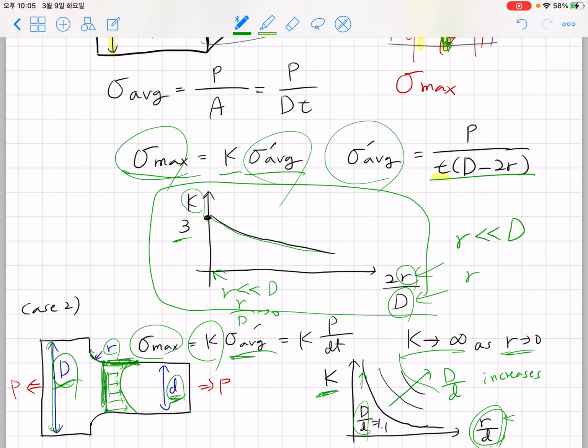Even though you make a one atom sharpness, each atom can have a finite radius. You cannot have infinite stress concentration factor. Of course, in the mathematical world, if you imagine a completely ideal continuum, you can have exactly zero radius of curvature at the corner, and you can have infinite stress concentration factor K.